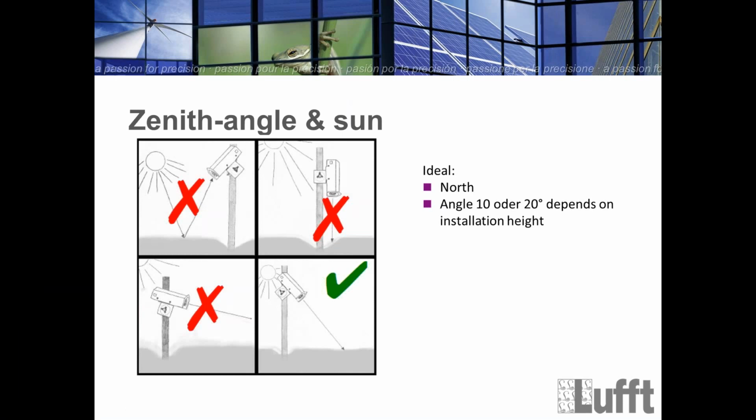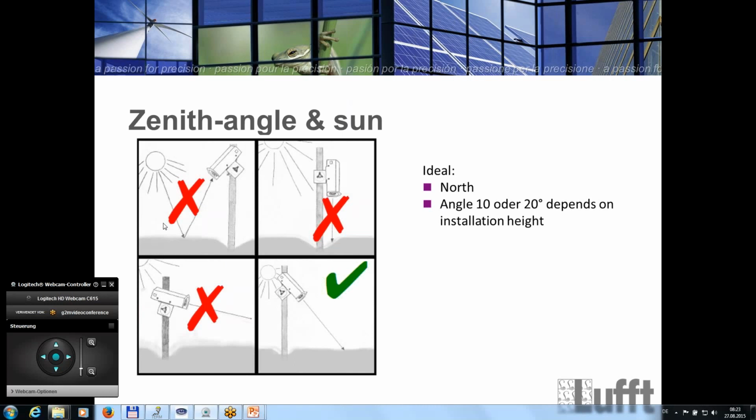The sensor can be mechanically installed on a mast, or you can also use any horizontal bar to install it. Keep in mind that, due to the sensitivity of this laser sensor compared to the ultrasonic sensor, you sometimes see the movement of the mast itself because of the very precise measurement with millimeter precision.